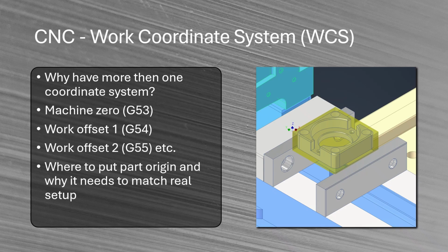I usually say, left is good because then you get positive X coordinates, and it's always best to put it furthest back. That's because this jaw is static, it will not move. And so it's often advantageous, you don't need to zero as often. Whereas if you put it here, this will change, of course.